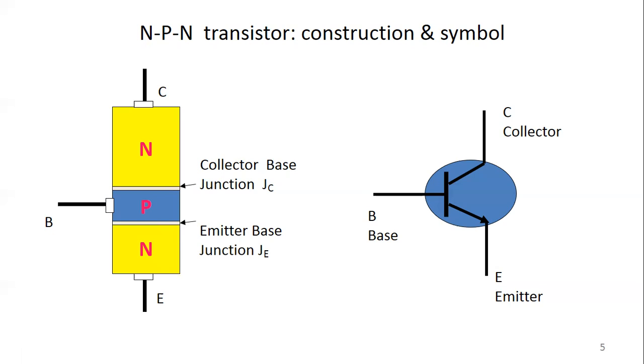And how can we vary this resistance? We have an input right here, a base terminal. To this base terminal we apply a certain biasing, meaning a certain voltage, and because of that these junctions are going to be affected. The depletion layer of these junctions is affected, conductivity is affected, so the resistance is going to vary, and we do our control with the help of the voltage or the current that we apply at the base terminal.